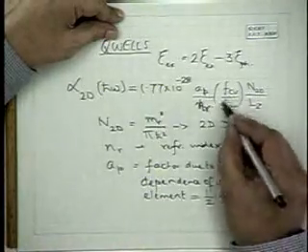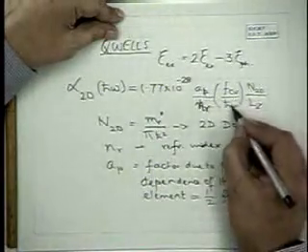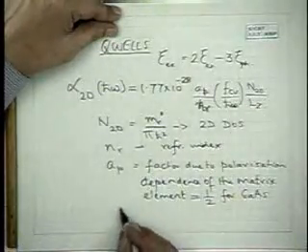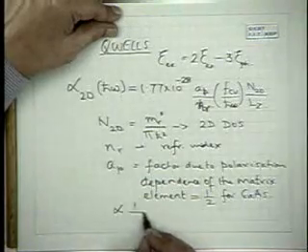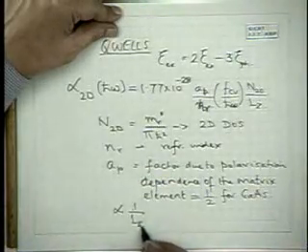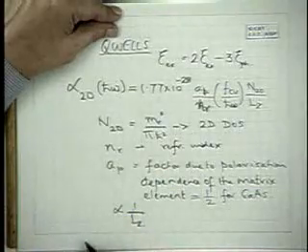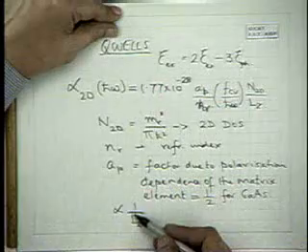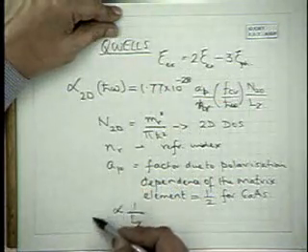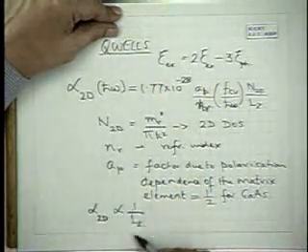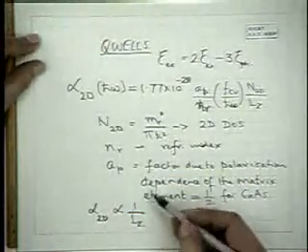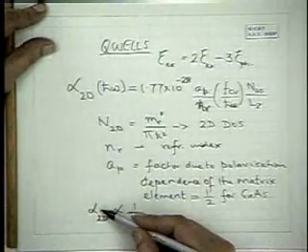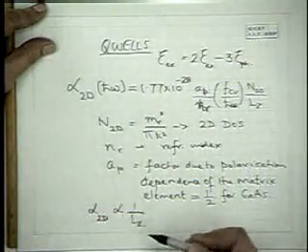And h cross omega is the energy of the photon. Notice that this shows that the absorption coefficient is proportional to 1 by Lz. The energies are proportional to 1 by Lz squared, but the absorption coefficient is proportional to 1 by Lz. So you would think that by having smaller and smaller values of Lz, alpha would increase, right? But this is not so.